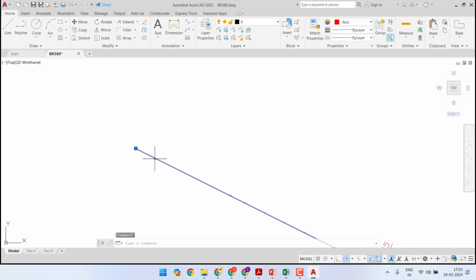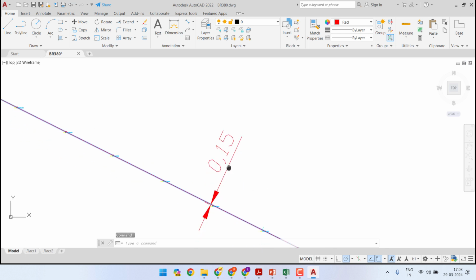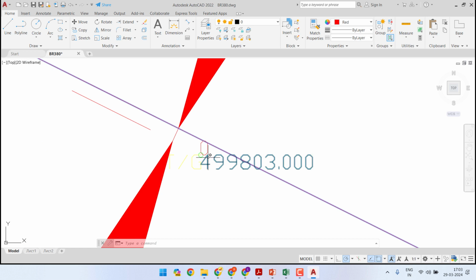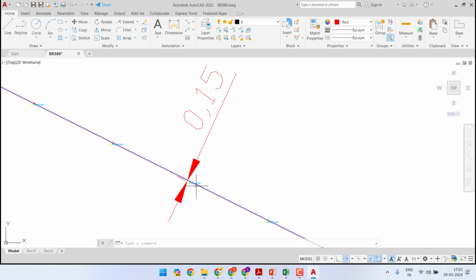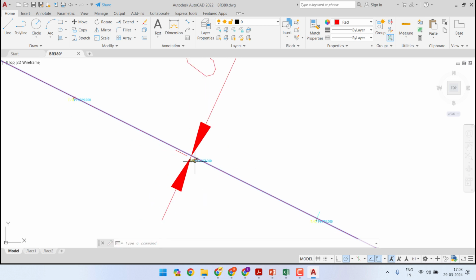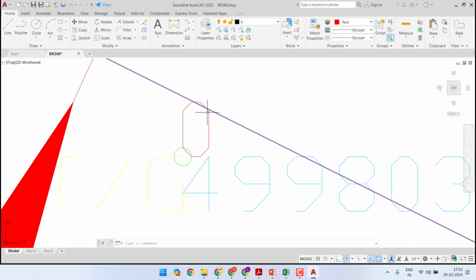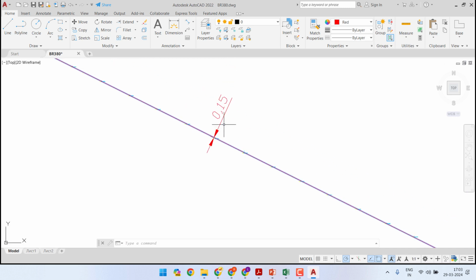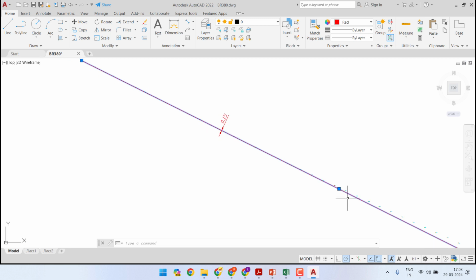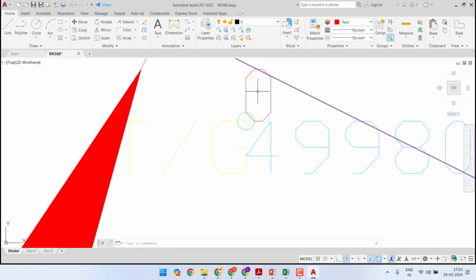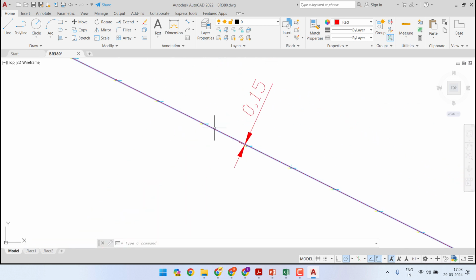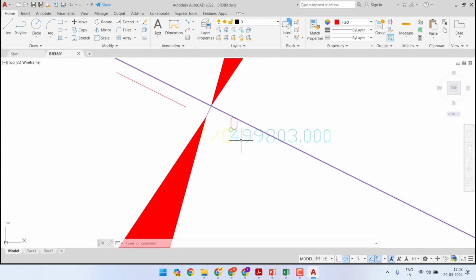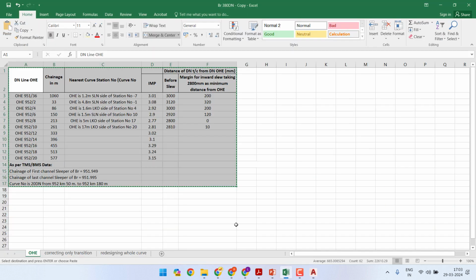So we have this first terminal tangent, and according to the first terminal tangent, the TTP1 of the curve is supposed to be 150 mm left. That is to say, to correct the alignment, we have to slew this point 150 mm towards left. Again, left and right are always with respect to increasing kilometer, the direction of increasing kilometer. So the person is standing here and looking towards increasing kilometer, somewhere looking towards this direction. And according to that, this point needs to be slewed. This point needs to be brought here. So the slew is towards left, and that is what we will enter here.